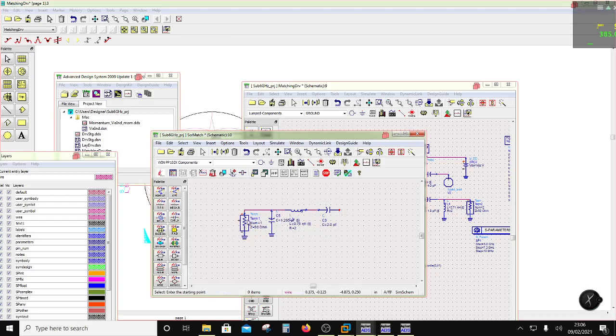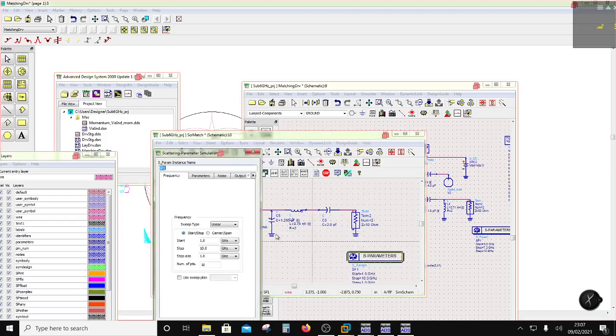So I have transformed 50 into a certain impedance. Let me see what that impedance is. If I go to S parameter and go to terminal, I want to look at S22. That is my impedance. So I go to S parameter and look at my frequency of interest, which is 5.8 to 7.2 gigahertz, correct?